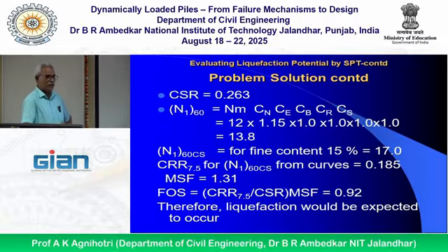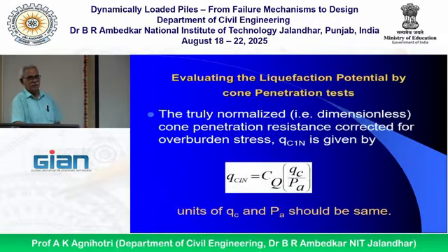So this is how we calculate the liquefaction potential. Wherever we go for soil investigations, normally we find out bearing capacity. We conduct the test, then we calculate bearing capacity based on shear failure, then bearing capacity based on settlement. That's all. But at the same time, liquefaction potential should also be seen, whether liquefaction is expected in that area or not. The same N values we can use for this purpose also. Then the cone penetration test. Based on SPT, we can have that.